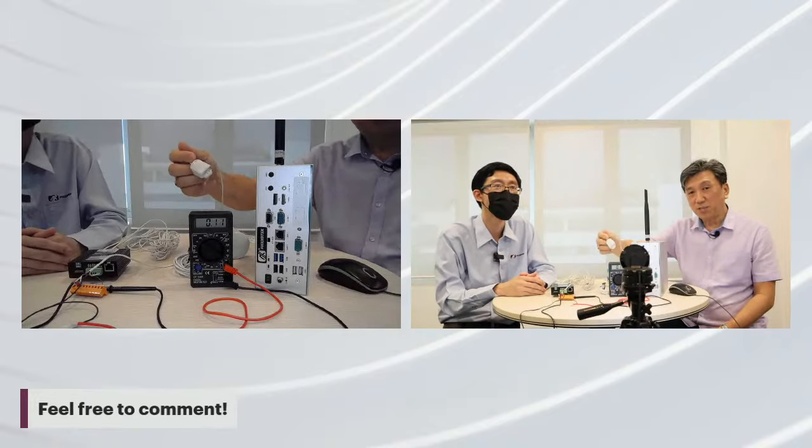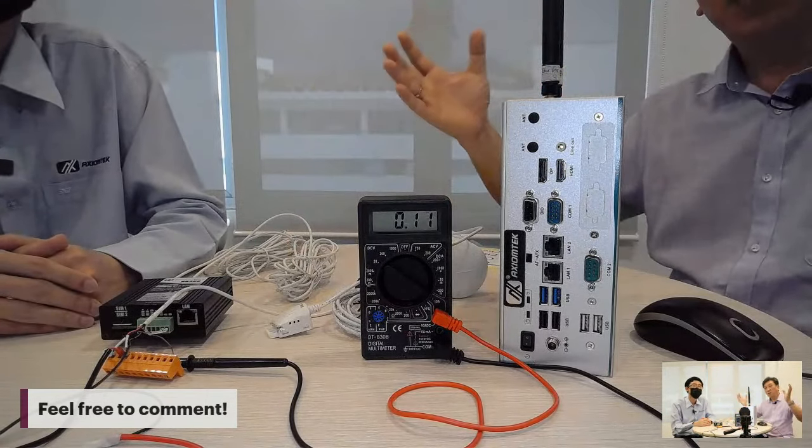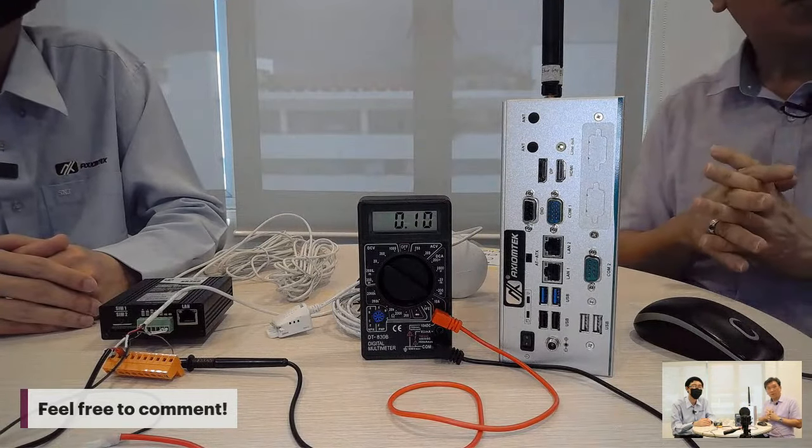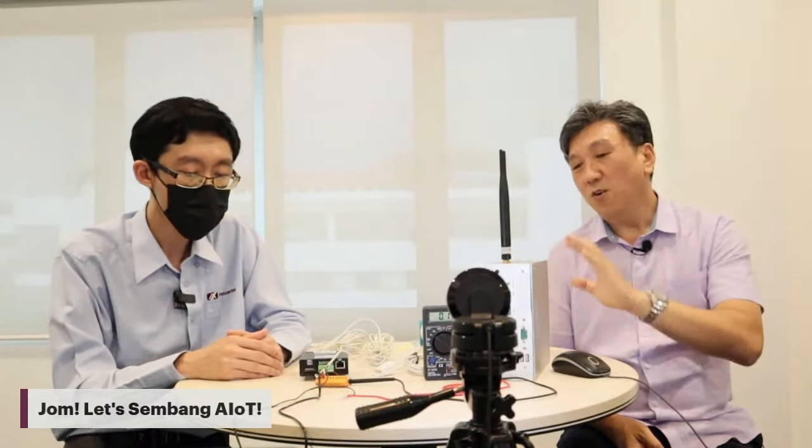Is there anything more that we want to share? Just one last thing: this is a very tiny temperature and humidity sensor. It talks Modbus RTU, that's why it's able to fit in there. Today we don't show our dashboard because last time we showed enough already. To recap, for example, some I/O points that you want to integrate into this device, you can have another I/O module with Modbus linking to this gateway or some of our IoT gateways, so you are able to publish data to the cloud, or if you want to publish to the server, also fine.